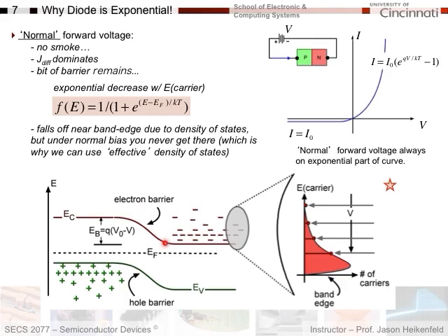As I increase my voltage, this goes down, right? This side decreases, and my energy barrier becomes less and less. And so as this is going down, it's the same as this going up, right? And so if I look at that, I first started that only these electrons above here could get across. And if I keep moving this down over here, then I can tap into more and more and more of these electrons. And we can see how mathematically that'll show up over here.